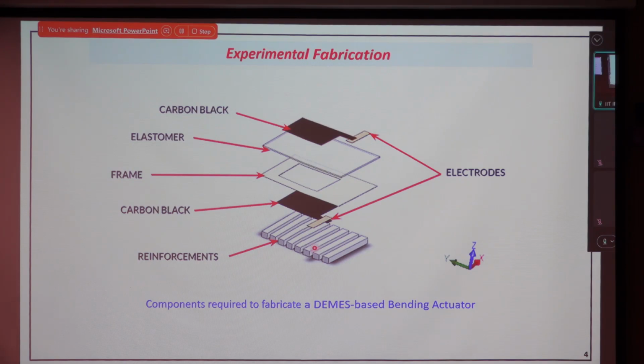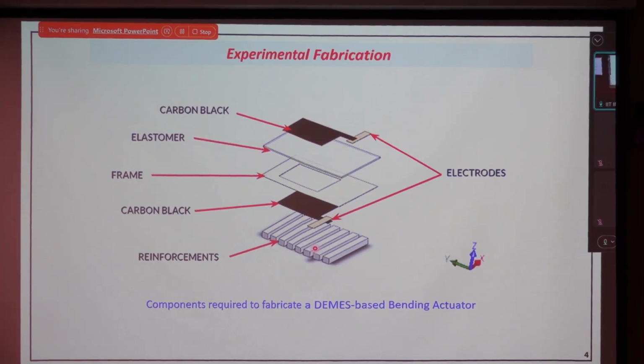So you can see, a problem arises, we find a solution, and that solution provides a certain advancement in your research area. We initially implement the stiffener to avoid warping, but we can vary the stiffener orientation to get different applications of the flapping wing. Getting my point? So stiffeners are also required. For a basic bending actuator, these ingredients are required. And for advanced applications, all the ingredients will be the same. Only the shape of the compliant frame that you are using is going to change.